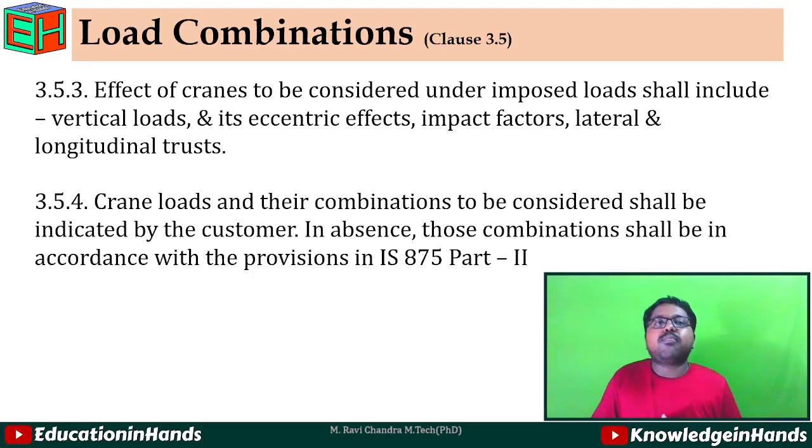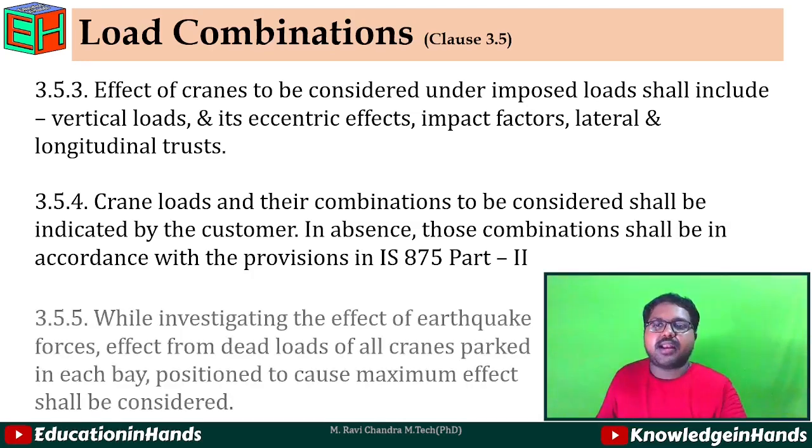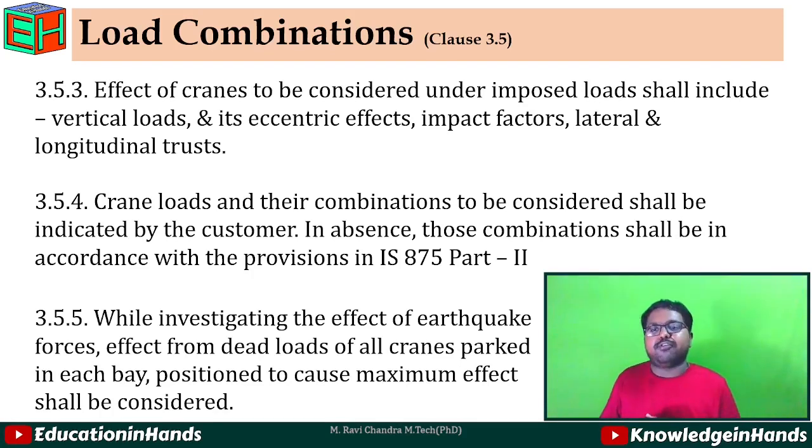Next one is 3.5.4. Crane loads and their combinations to be considered shall be indicated by the customer. Otherwise, in their absence, their combination shall be considered in accordance with the provisions given in IS 875 Part 2. And then in 3.5.5, while investigating the effects of earthquake forces, effects from dead loads of all cranes which are parked in the bay and positioned to cause maximum effect will also be considered. So all these combinations and guidelines are clearly given in the IS 800-2007 clauses.